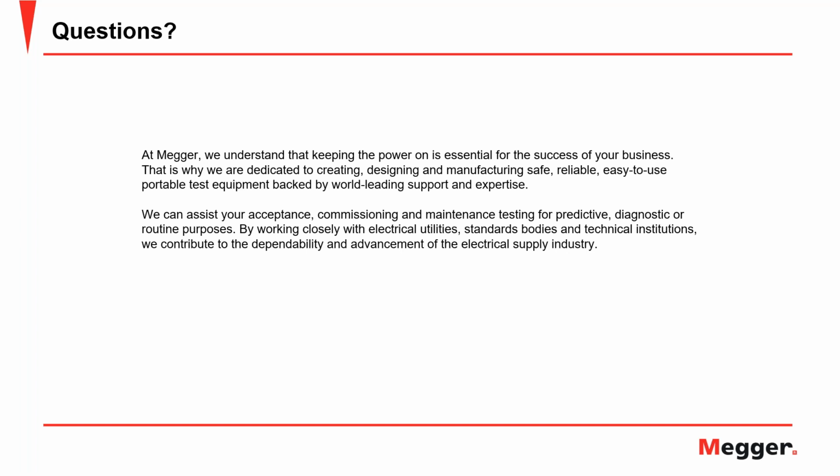Sanket did show some of the accessories, and one of them was the hot collar straps. Those are semi-conductive straps, and depending upon the size of the bushing, you may perform 1, 2, or even as many as 5 hot collar tests at different levels of the bushing under the petticoats that Sanket mentioned.